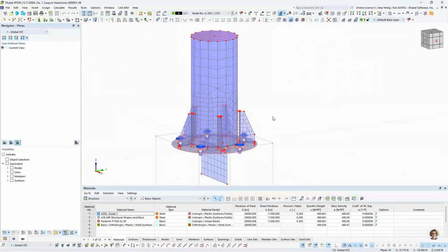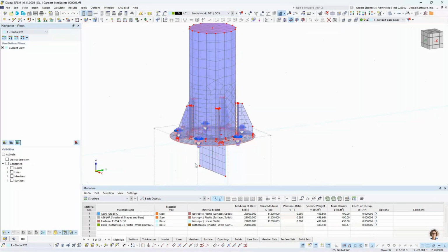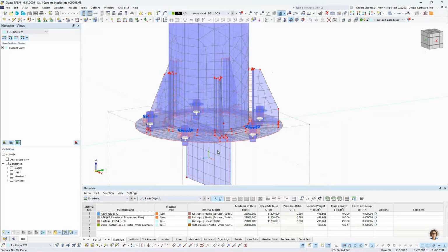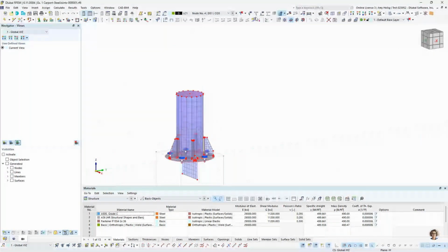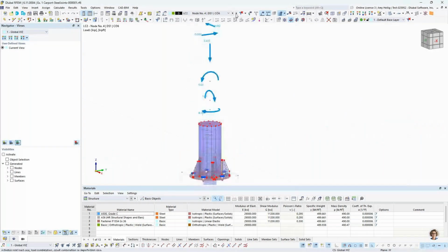connection components. Everything is a nonlinear material. We have a lot of geometric nonlinearities as well that are taken into consideration, but all of the bolts, the welds, the plate elements are modeled with the relevant FE mesh size, again, all underneath the hood. You can see here the member end forces through each one of these load combinations that the program is running through in order to come up with that design.